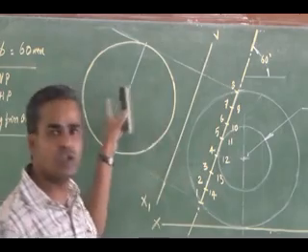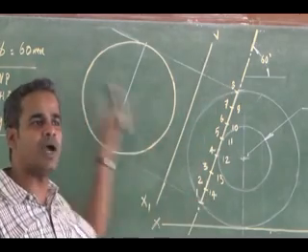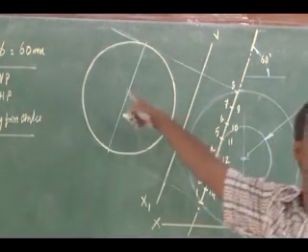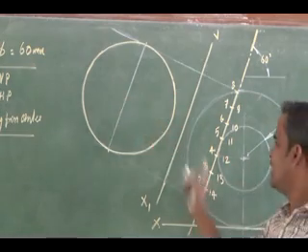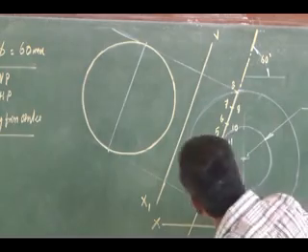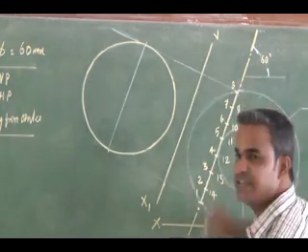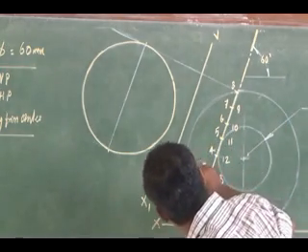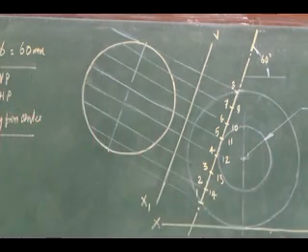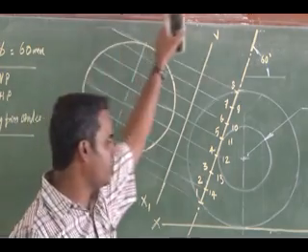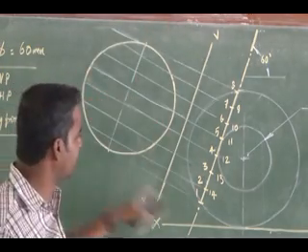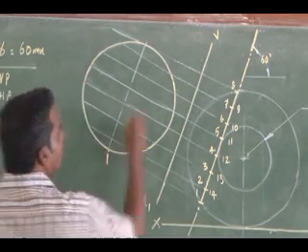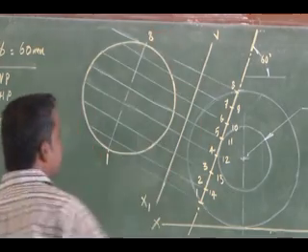Now the true shape normally we will be projecting from these cutting point locations. We know the true shape is already drawn, so I can mark these cutting points on my true shape by projecting. Here I can mark these cutting points, the visible cutting points and the hidden cutting points, all the 14 cutting points, in an order. Right, this is going to be my cutting point. One location, the other 8.